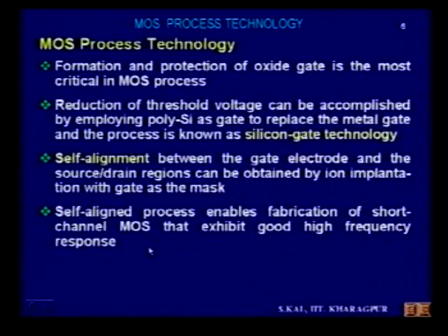Short channel and long channel MOS are two categories. The only difference is that the channel length is small in the case of short channel, and I will show you later a table of how much channel length is used at present and how much was used a few years back. Short channel devices obviously have certain problems, and we have to overcome those problems by incorporating certain techniques in process technology.